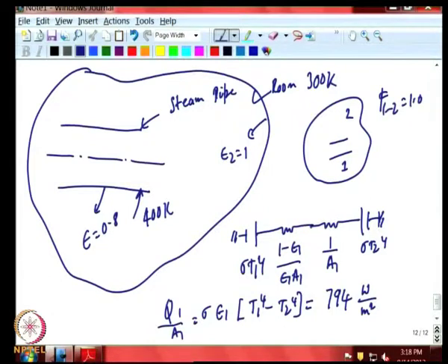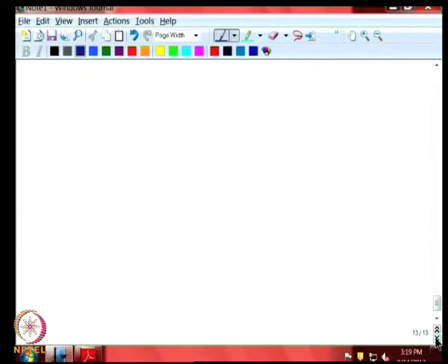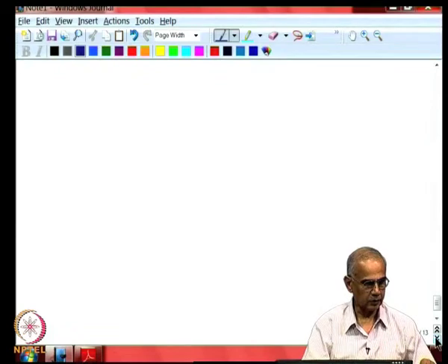So, this heat loss is more than the heat loss by free convection from the steam. So, it really is useful now to add some insulation on the steam tube, reduce the heat loss not only by conduction, but also by radiation. Okay. So, this is one example of typical application in the industry where a pipe containing steam going long distances will cause large heat losses, which are inevitable.